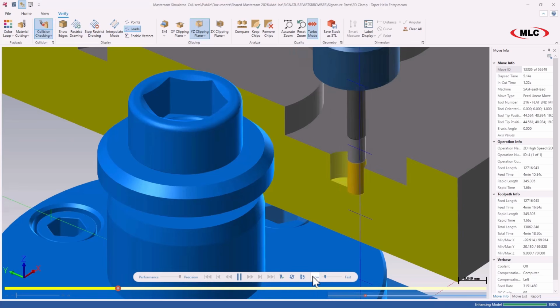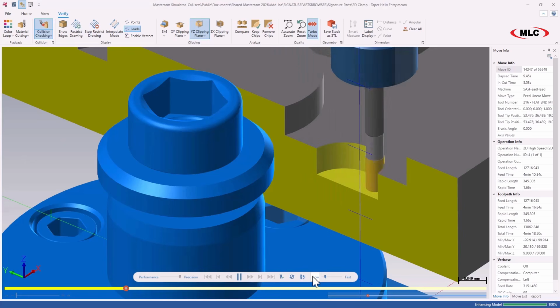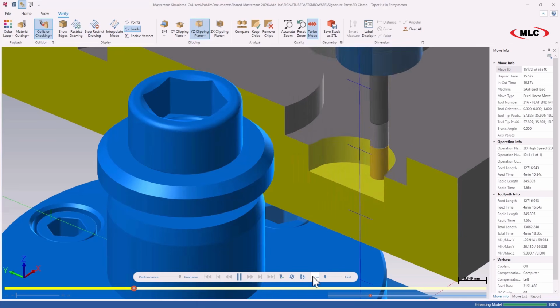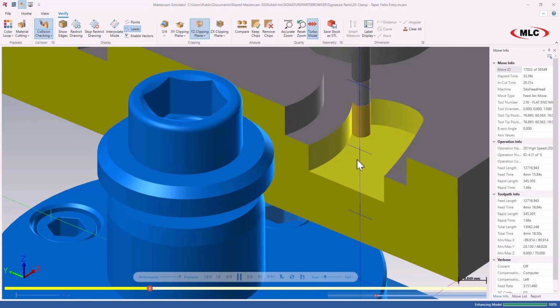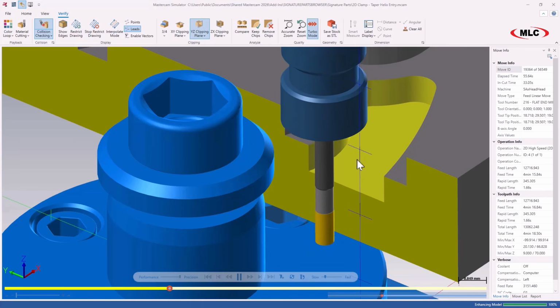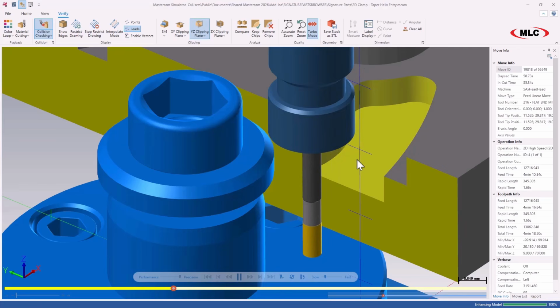And when it reaches the final depth, notice how as it opens up, it's actually engaged in a small section of the flute and slowly increasing the section of that flute height all the way until it reaches the full radius value of the top section, and then starts to open up the pocket in a normal dynamic mill pathing operation. And the benefit of that is that now as it's opening up that initial helical plunge cavity, it's allowing chips to get flushed out quicker and easier, and allows the coolant to reach the bottom of your tool where it's really making contact with all that material, right?